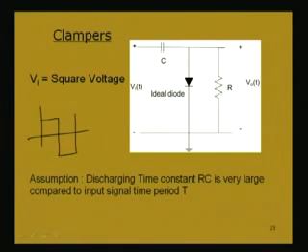And for simplicity, easy understanding, we first consider an ideal diode. An ideal diode has 0 drop and resistance is ignored. We are applying, suppose, a square wave, that is, this type of waveform. It is an AC, no doubt, but this peak and this peak are exactly equal and it is square.